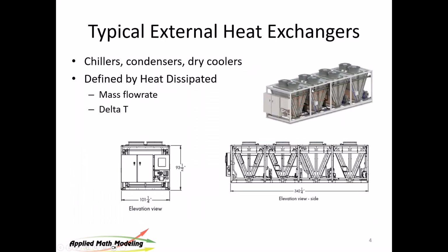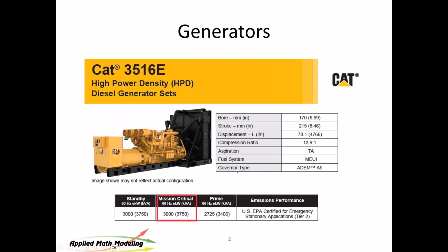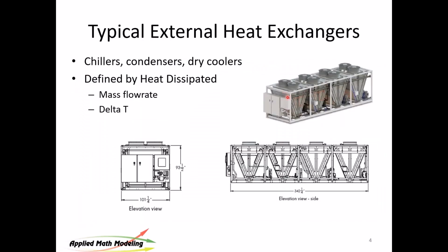Now, it's not perfect because you see these are angular and this is flat. But in the greater scheme of things, what you're looking for is what's the approximate temperature coming into these devices. And here we're going to get the approximate temperature of that inlet of that PDU, or in this case, HDU. Here you would really want the temperature along these sides, but again, these are not constants, they vary, and the reason we're doing it rectilinear instead of as an angle is mesh size, mesh count.